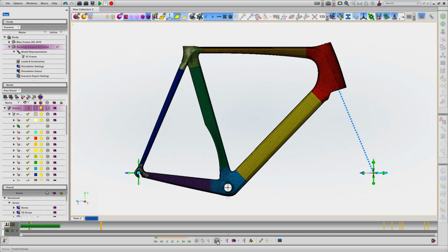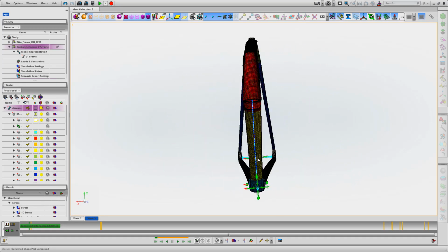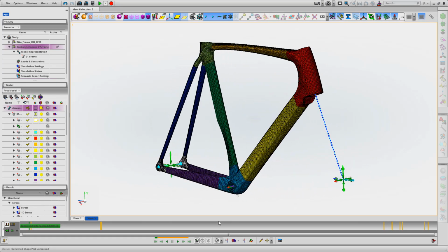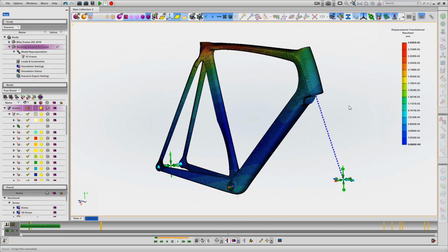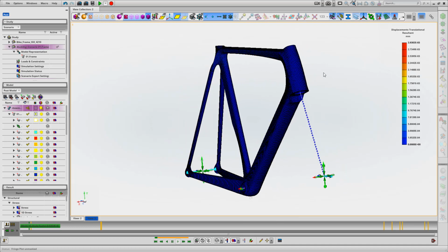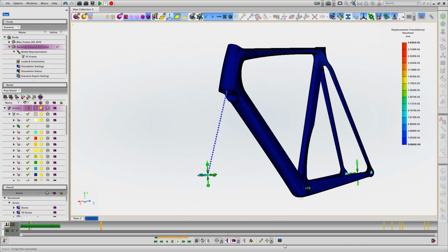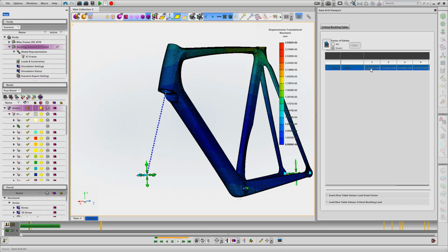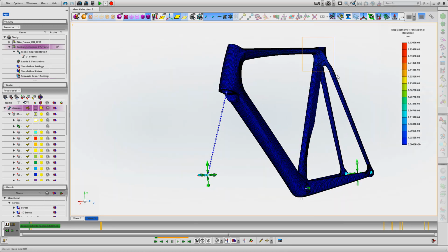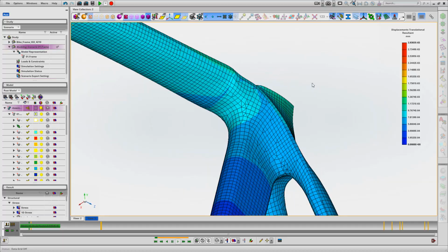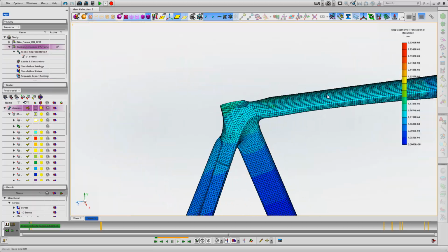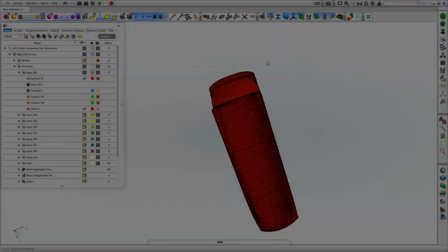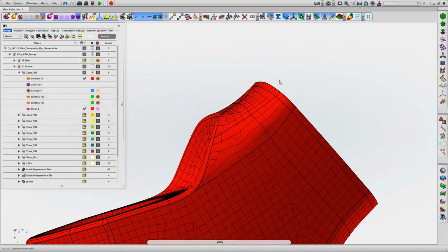Lots of information that Apex gives us. We can run different load types as mentioned. So this is a stability case, so a buckling case. We can look at the displacement and the load factors that are developed for this kind of analysis, and see here a table of values that's generated. And we can see here the peak displacement is at the interface between the sort of thinner section of the top tube where it meets the stiffer seat mount or seat junction.